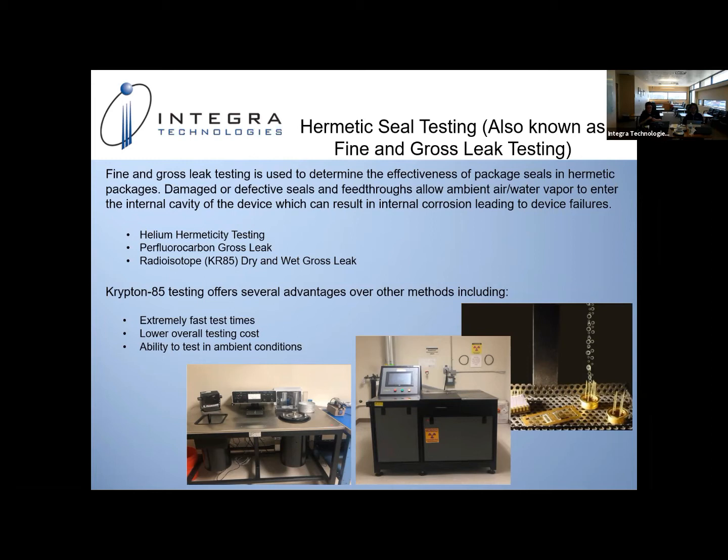Several test methods are available: a helium fine leak test, perfluorocarbon gross leak testing, or radioisotope KR85 type testing. KR85 testing offers several advantages over standard helium testing, the most notable being quick turn times.